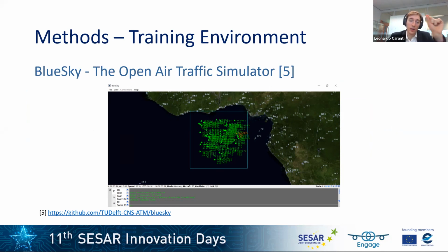As I have previously mentioned, in order to obtain the true number of conflicts, a simulation was used with BlueSky, the open air traffic simulator. This tool has an airborne separation and assurance system to which many different conflict detection and resolution algorithms can be applied. This does allow for them to be tested under the same conditions, if one would want to.